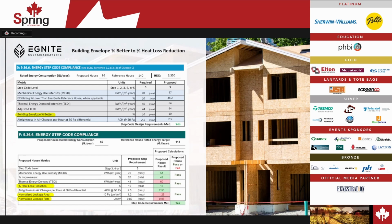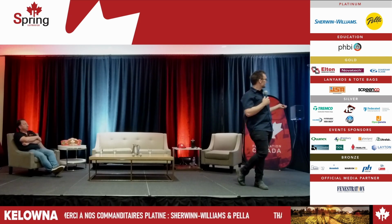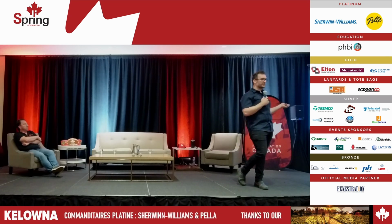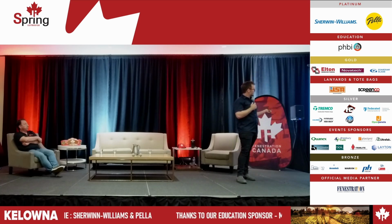Under the Energy Step Code compliance metrics, we used to have building envelope % better. And the one thing with the building envelope % better, it was accounting for passive solar gains. So if we had a building which had majority of the windows facing south, it was passing quite easily underneath building envelope % better target. That has now gone away underneath the revised metrics.